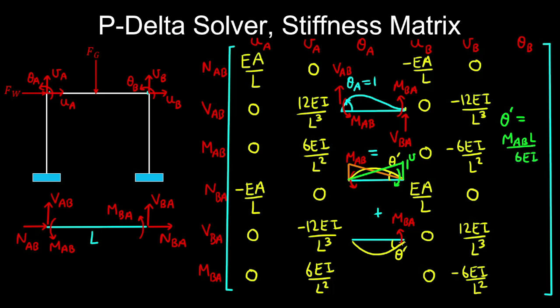And if you do the same thing for our second case, so we have the real bending moment being equal in magnitude to MBA and drops off to 0, and applying a virtual moment at B, our virtual bending moment diagram looks something like this. And the volume between these two triangles is MBA by L on 3 EI.